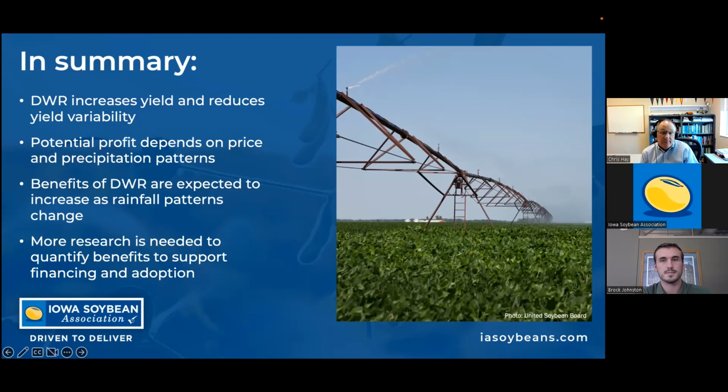But storage is really going to depend on if you've got a spot where you can create an embankment dam, that's going to be cheaper. If you've got to excavate it all, that's going to be quite a bit more expensive. And so it's really hard to put a good rule of thumb number on what the storage is going to cost. That's really going to vary from site to site.